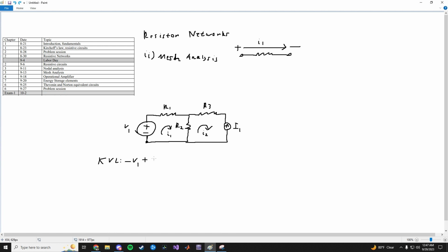So it'd be plus I times R1, because remember, that's Ohm's law, because Ohm's law is V equals IR, or V equals R times I, which is how you do the KVL. You use V equals IR. So that's the voltage across this resistor, plus, well, I'm still following, I have this resistor here, following the arrow, this R2. So for this one, it's going to be I